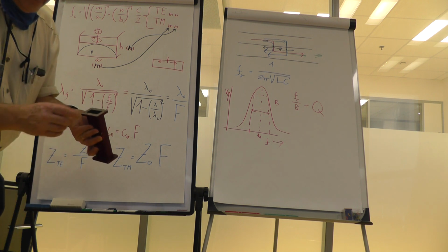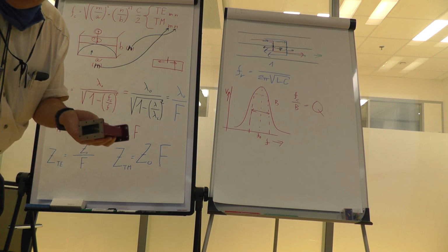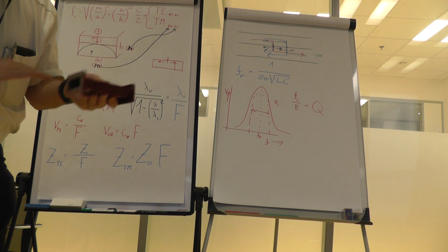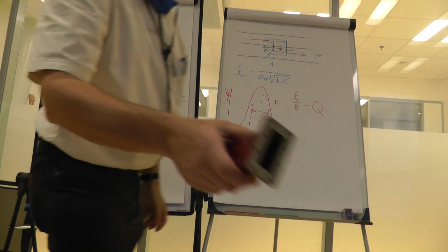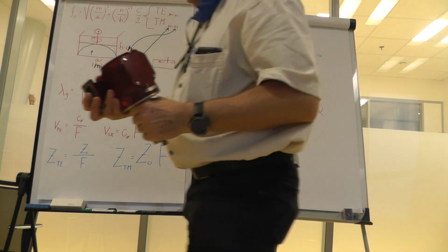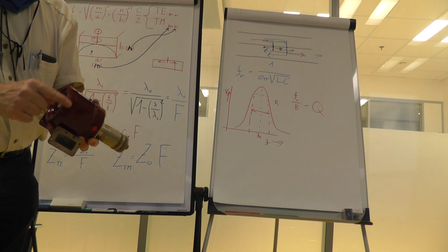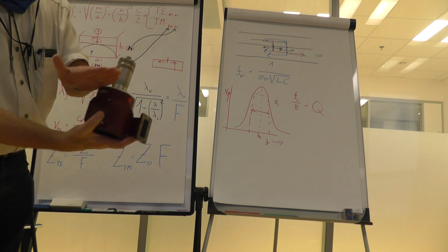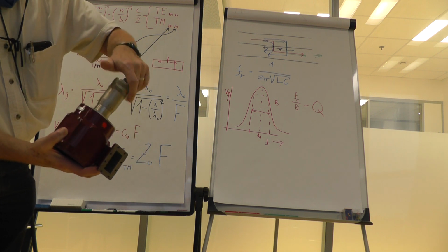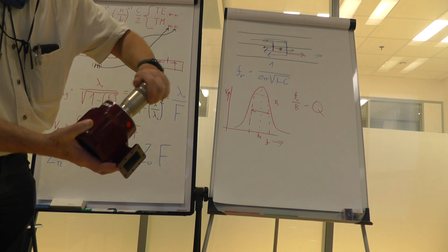And if you cover those walls with well-conductive material, that is silver, and you fine polish it, you could get high quality factors. For example, a kind of resonator like this would be a circular hole, and you have there a piston moving up and down with high precision. You have a precise screw that could position the piston in the proper position.